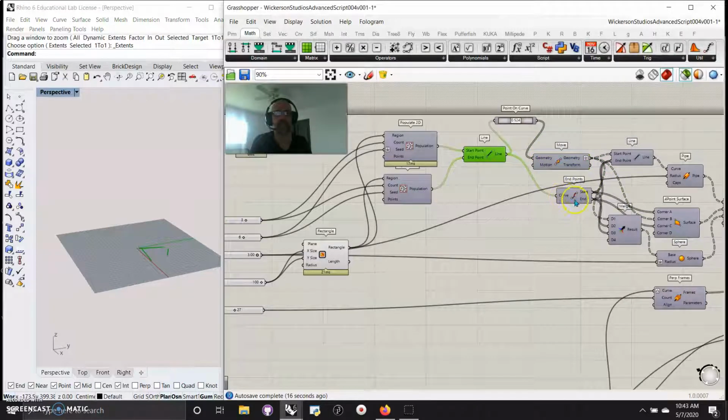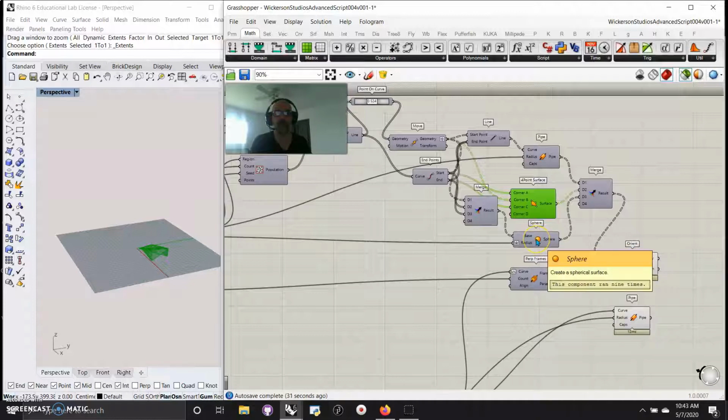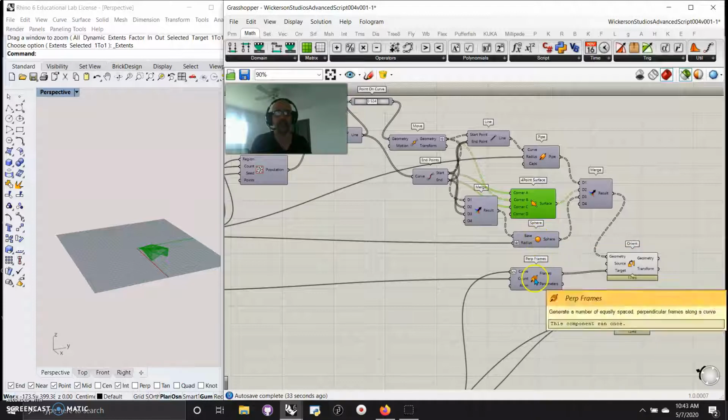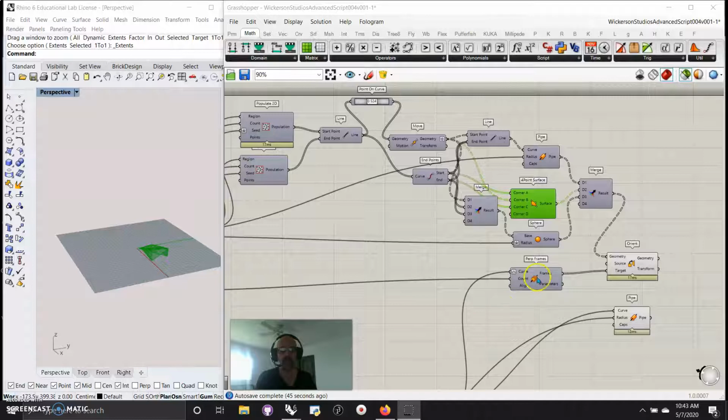Going back to these lines, I also want to grab the start and ends of those lines. And I also want a line going between all of those points and all of those geometries. Then I bring them together, and I pipe those. I surface those very close to what's happening in Weaverbird and other functions and other plugins, but I like to do this from the very basic Rhino Grasshopper 5 Mac files that I have on my laptop. It keeps things simple, and then when people download my files, they don't have to bring in a bunch of plugins. This is kind of introductory.